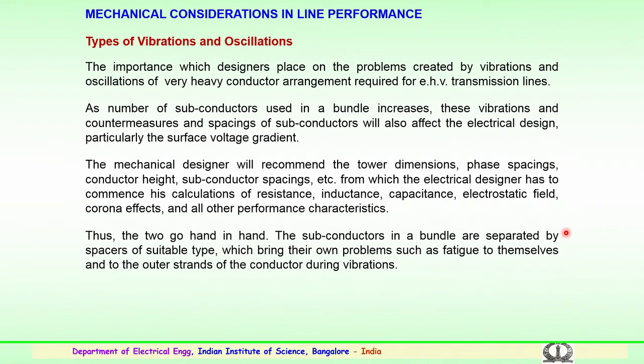If it is a twin spacer, if it is a quadruple, that is a 4 bundle conductor, it will be a quadruple type of spacer. This brings its own problem such as fatigue to themselves and to the outer strands of the conductor, particularly during the vibrations which the conductor bundle experiences. So, important considerations for the design aspect.